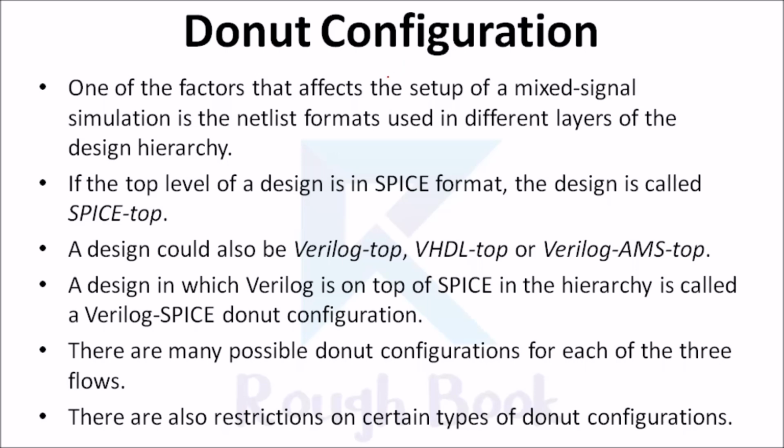This netlist format can be Spice, Verilog, VHDL, or Verilog AMS. If the top level of the design is in Spice format, then the design is called Spice top. Similarly, if the top level of the design is in Verilog format, then the design is called Verilog top. The same applies to VHDL top and Verilog AMS top.